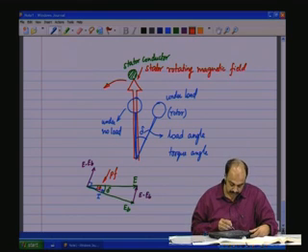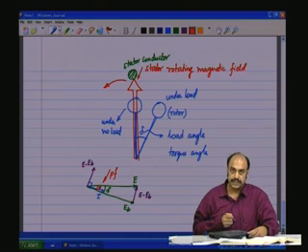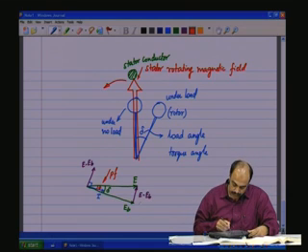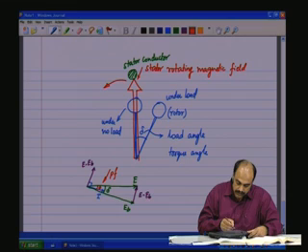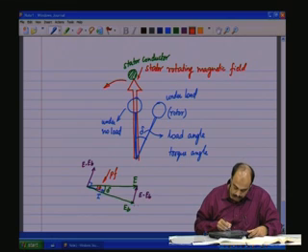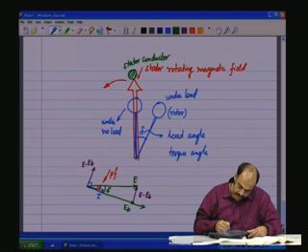So we see that a major portion of the active power goes on to the shaft, and the power factor angle can be controlled by controlling the amplitude of EB here. So by controlling the amplitude of EB, let us say if we make EB more, you will have E minus EB like that, and you can have a current just 90 degrees.